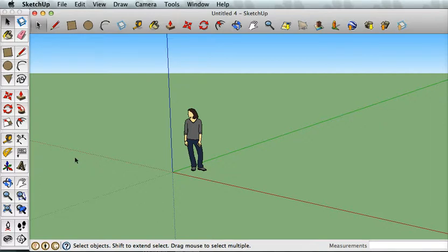Now if you haven't selected this template, then the easiest thing for you to do might be to close SketchUp, start it again and select the appropriate template. The template that you need is architecture and you need to be working in meters.